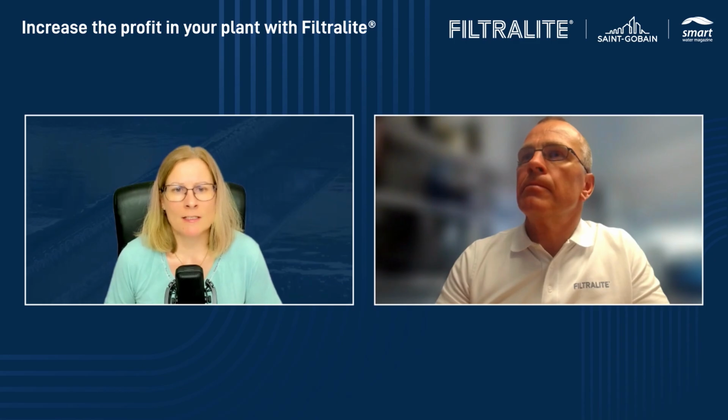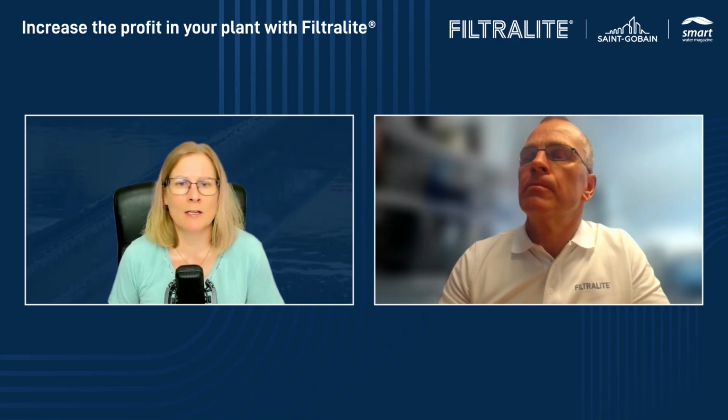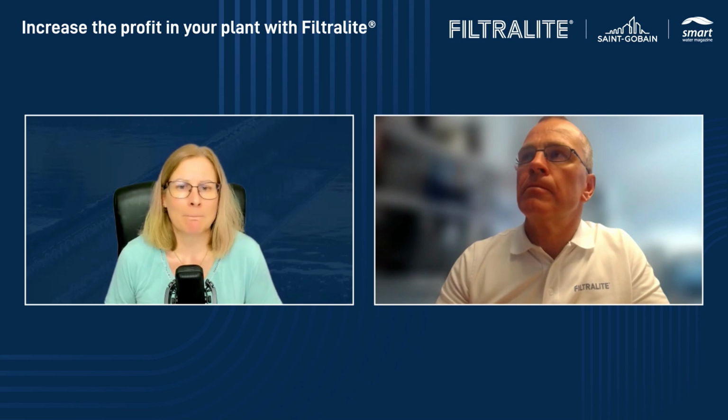And the question is, has any testing been done to compare Filtralite with new anthracite of the same size? For example, 1.5 to 2.0 millimeters. And his comment is, I would expect that a coarser material would improve filter capacity, so lower head loss, but without long-term data, the increased capacity might be short-lived.